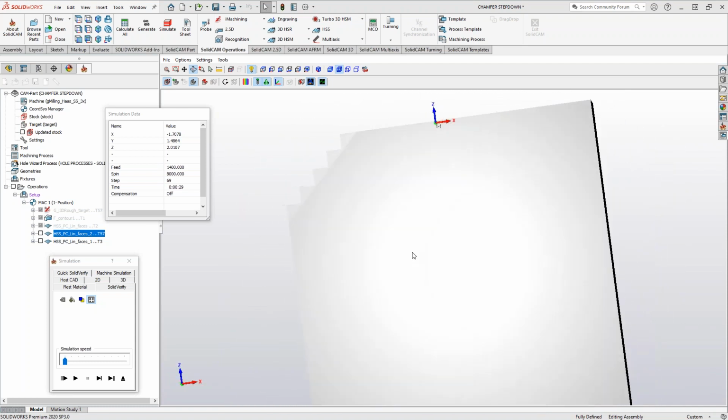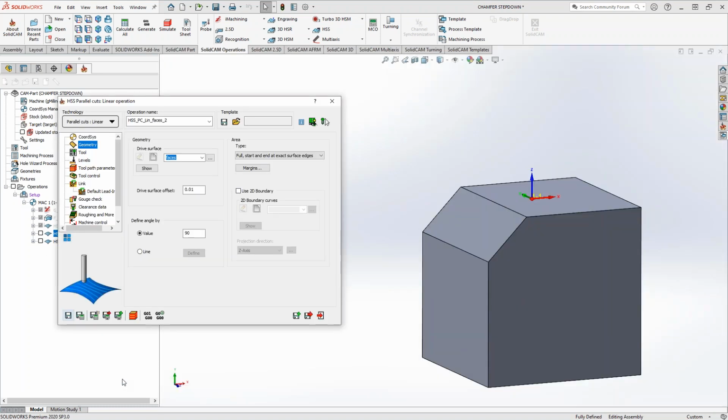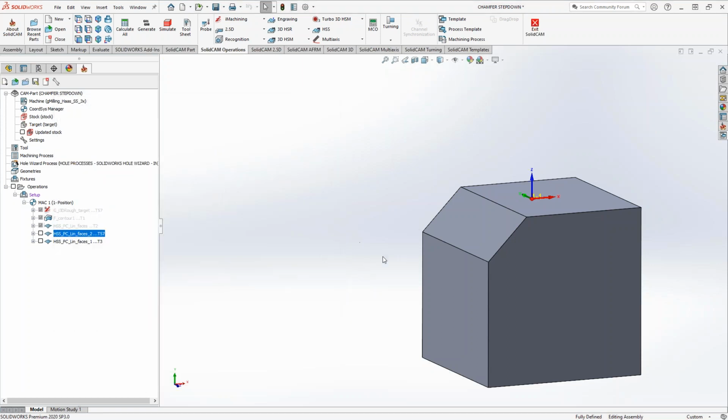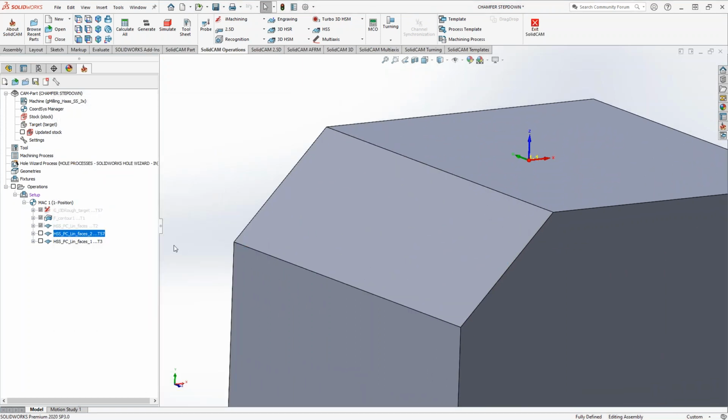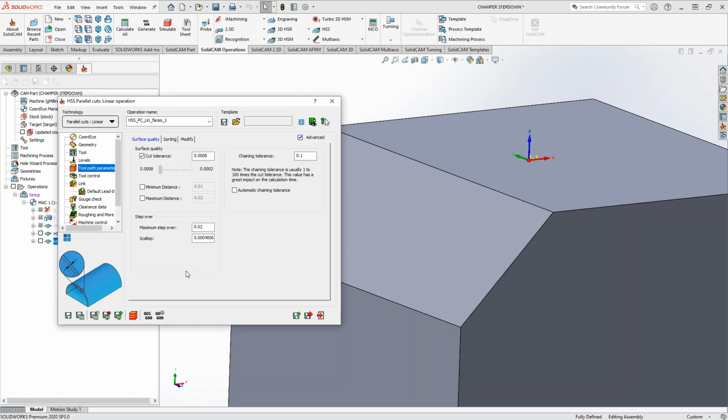And it all depends on your print. Sometimes when they have a weld, they want a specific surface finish. Sometimes if you're just doing it in house, which we did, that surface finish did not matter to us as long as it was filled up with weld, and then we'd come back over it with a grinder and grind it. You would never even know, and you still get that great weld penetration going on there.